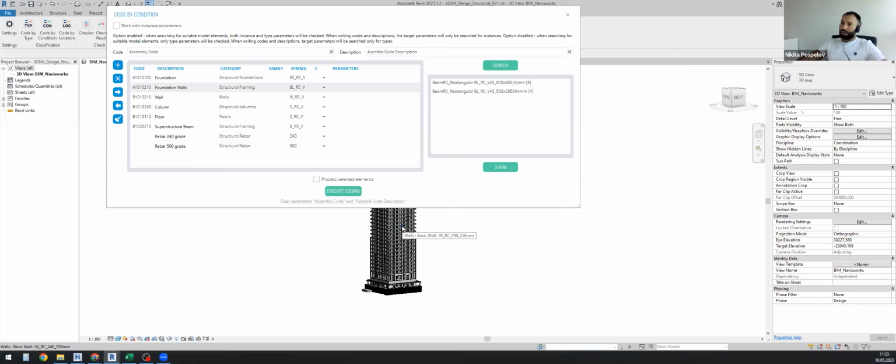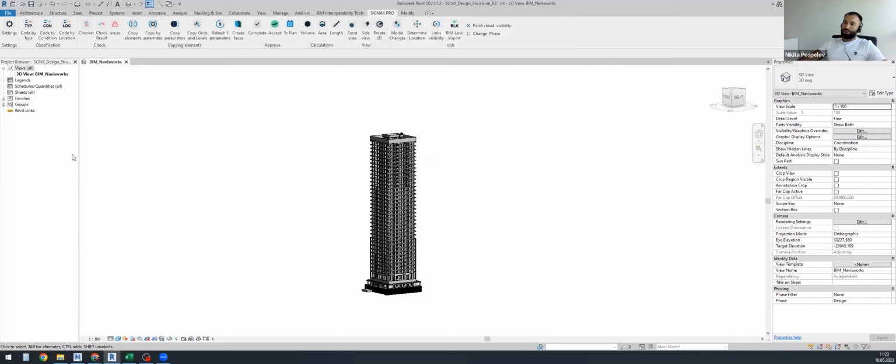After that, you can continue to work with the BIM model inside Revit or export it to a Navisworks file and create, for example, automated search set creation and calculate the scope, the budget, BOQs, or invoices using the assembly code inside the elements. So these are two features that can easily help you to create assembly codes inside the elements.